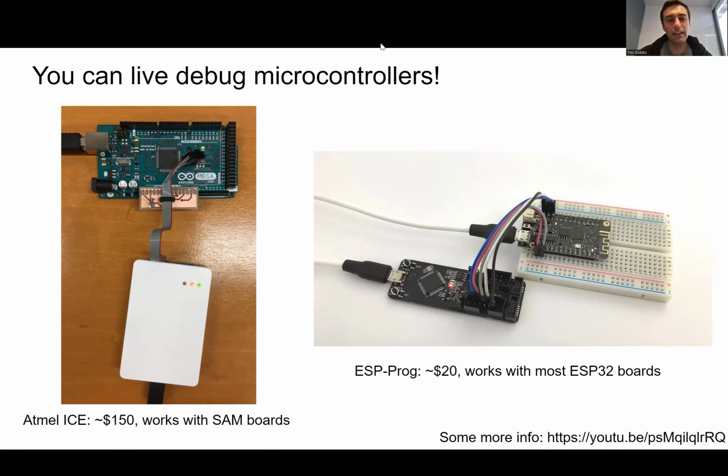But I really like all the tooling that comes with FreeRTOS, and having already started to think that way, I found it's easier to keep thinking that way. Also the delay thing is so great, because when you're programming microcontrollers, even when I was doing hobbyist stuff years ago, you're constantly having this problem where you realize, oh, I need this to wait 1 second, but now it's not responsive. If I want to press a button, it won't respond until it's finished waiting 1 second. So I really like the tooling for that.